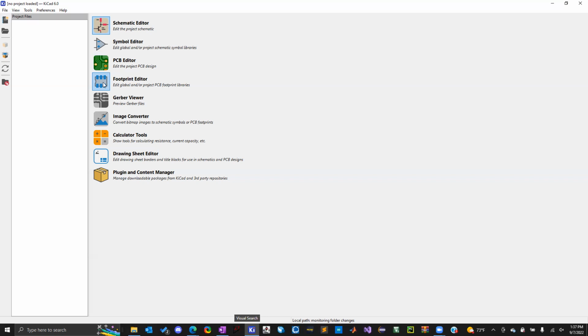The other method is you can have a component that just has a pad or a layer of copper on it, and you just match it over the layer of copper on the board and then solder that. There's a lot of ways to solder it on if you're doing it manually by hand. I've seen a lot of methods. My favorite is by using soldering paste, but you do have to be careful because depending on the distance from each of the pins, you can't have any of them bridged to the other, or else it's not going to work. That distance between all chips is usually known as pitch.